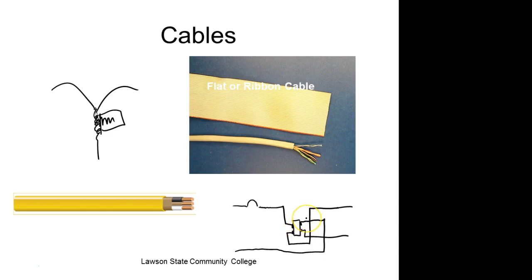This is real fast. In fact, we've come up now and they've got these compression plugs in the back where you just strip the wire and stick them in there. And you don't even have to screw the screws down. And those will wear out over time, guys. So I would never, ever recommend using those things. But they're available and they're legal. And they'll just strip the wire and stick it into that compression plug, and it's got little fingers in there that grabs it.